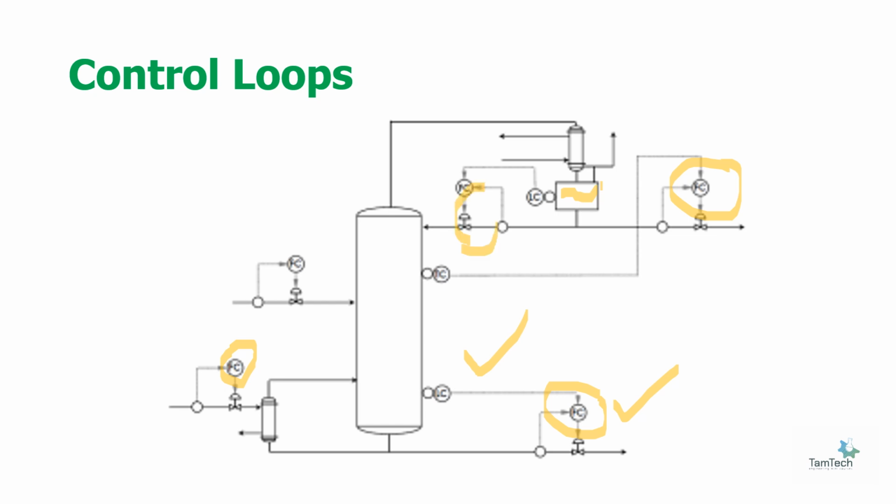Sometimes a pump is also used, like here, and you could control your pump speed, the level of the overhead accumulator, sorry. And you have in addition the flow rate control at the inlet of the distillation column. This is a very generic picture, but in general in industry it is, I would say, much more difficult and much more complex than this.